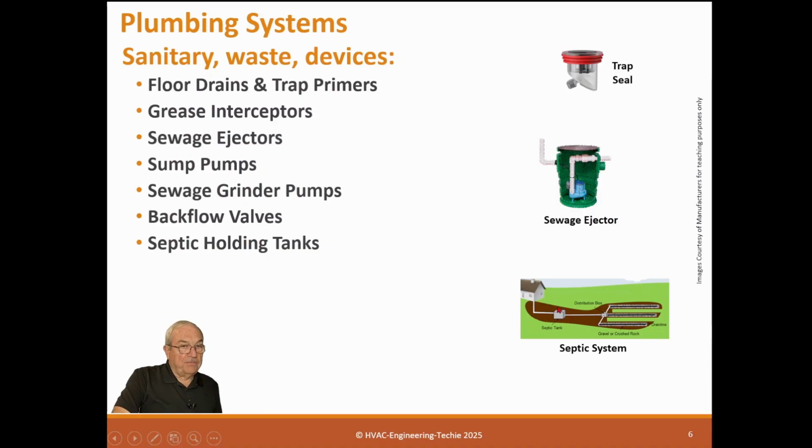And you have to pump these every 10 years or so. You have to come in and pump the septic tank to empty it out. And there are some rules about what you should use in the house or in the commercial building that has one of these, because certain things, if you put them in, will kill the bacteria in the septic tank, which is what you want. You want good bacteria in it that's digesting the sludge, and it falls to the floor. The bottom of it is solids.